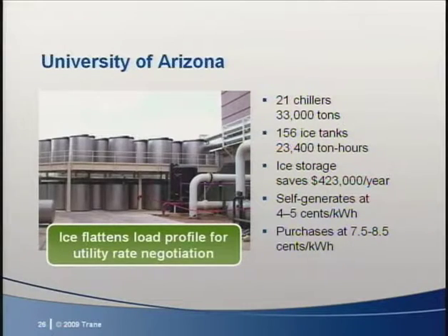For an example, we turn to a familiar installation. The University of Arizona is a great success story on many fronts, and their ice storage system is no exception. The U of A uses on-site power generation, so they are fully aware of the importance of having nighttime electricity consumers. By making ice at night, there's a much more constant loading of the power generation equipment. This drives down their cost per kilowatt and creates heat recovery for their steam plant.